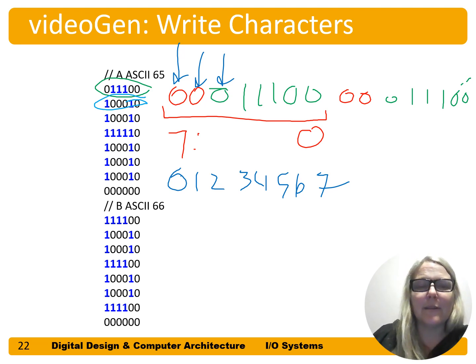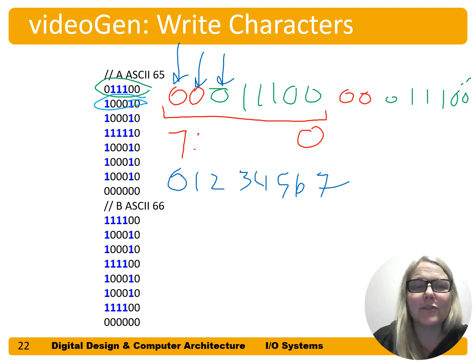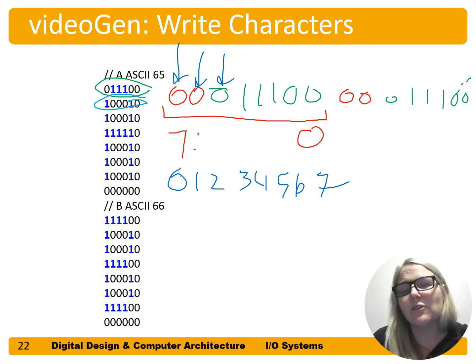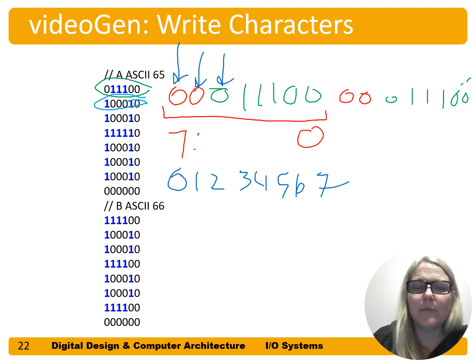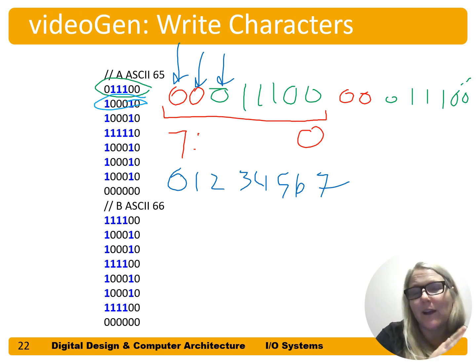All right, that's it for VGA. Mostly focus on the basics of VGA, which is everything except for the character generation. This one's a little bit more tricky than the other ones. So when you're first learning about VGA, focus on how VGAs work, and then the first 2 examples that I gave, just drawing a very simple one where we just display a blue area on the screen. The one I showed was a vertical area, actually on the right side of the screen.